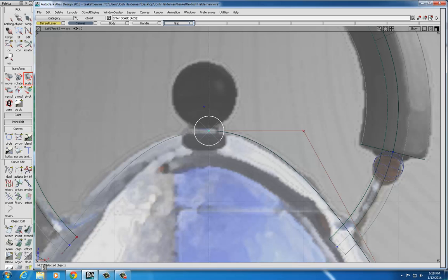Next, I'm going to rotate this into position, and this is rotating around the x-axis, so it's 90, 0, 0, because right now we're looking at the cylinder from the top. Now we're looking at it from the side. Now I can scale it down, and I don't want to do it horizontally. I want to make sure I do it vertically, because remember, I just rotated my object.